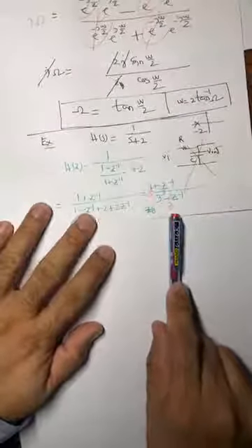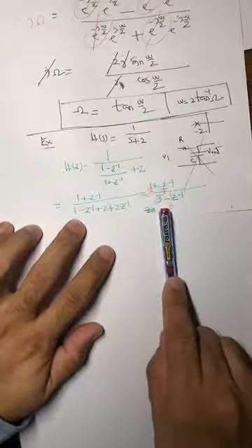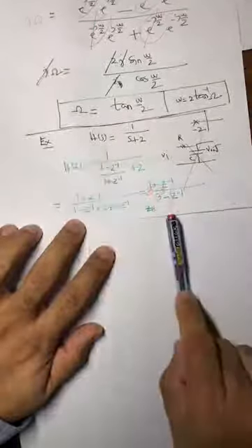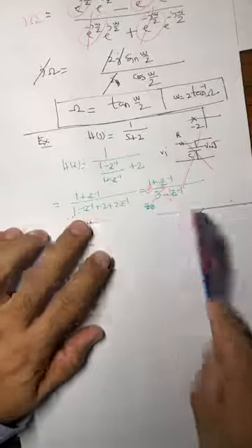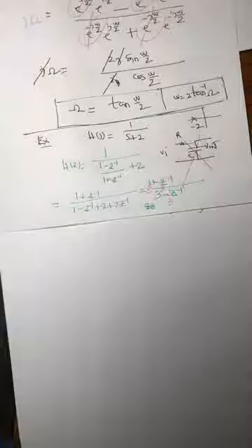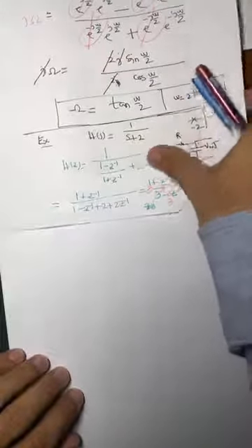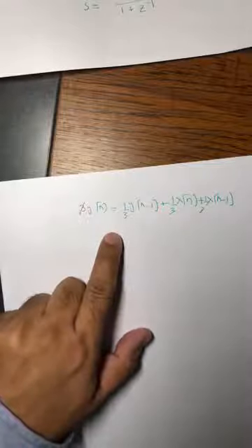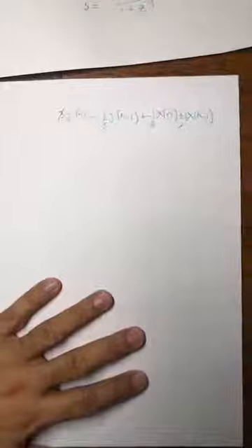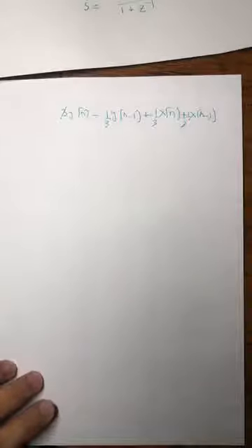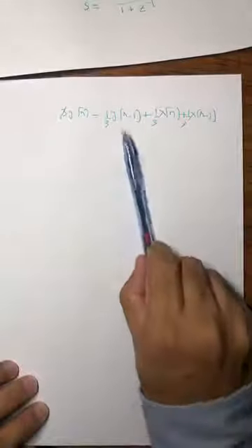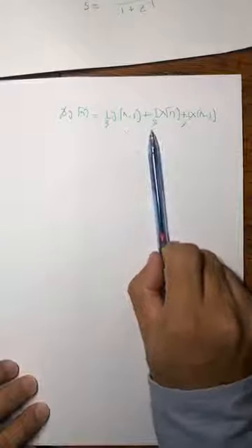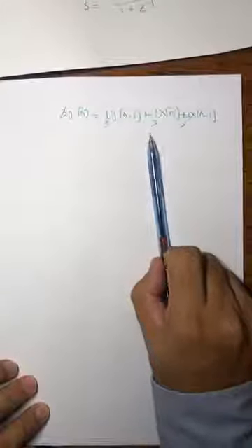Another thing you see is that this 1 over 3 is less than 1. So a pole in the left half of the s plane guarantees a pole which is less than 1. This is because for the transformation to be valid, a stable system must result in a stable system. So this is the computer program which you write. At this stage of the course, and even if you have not taken this course, you can implement an equation like this. So this is good.